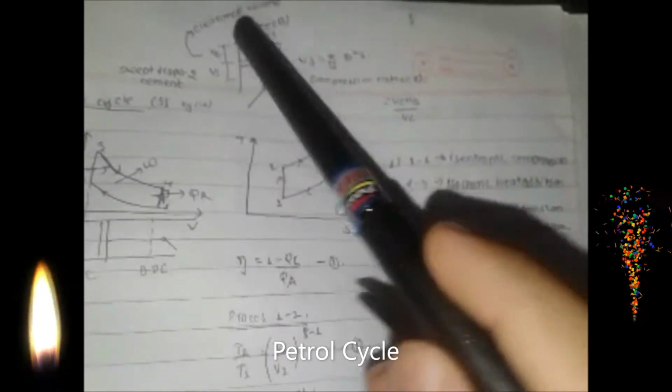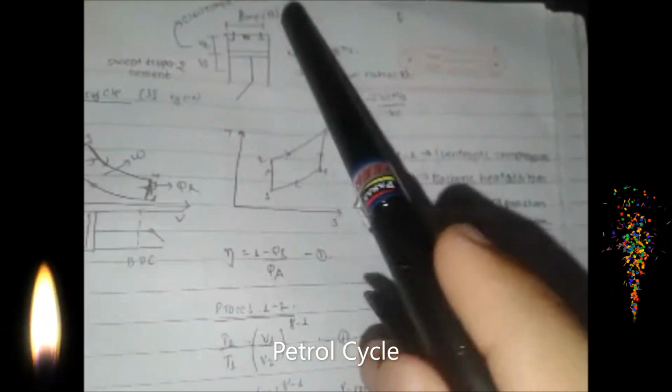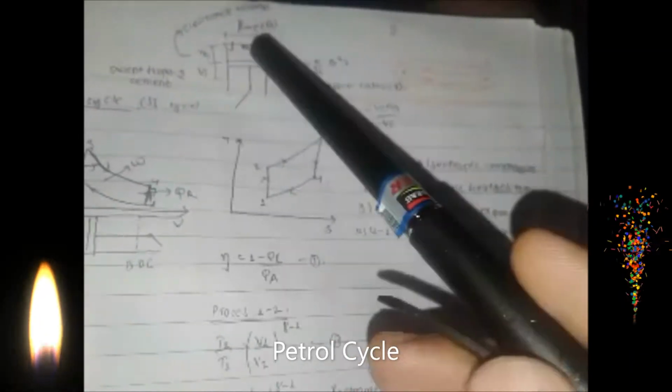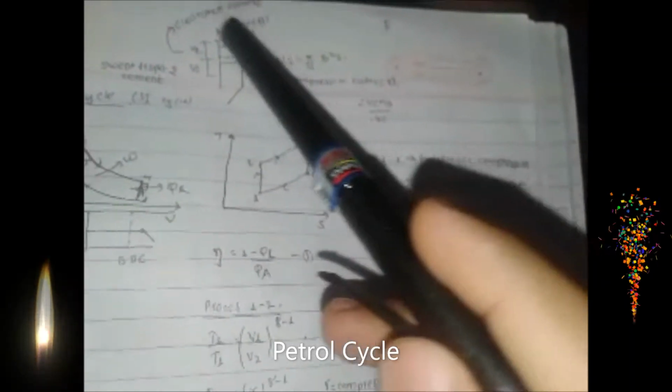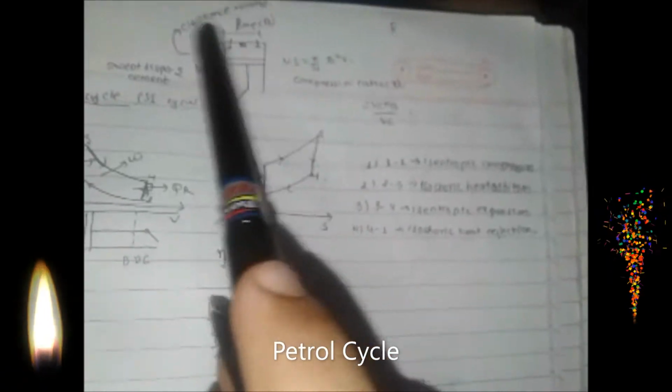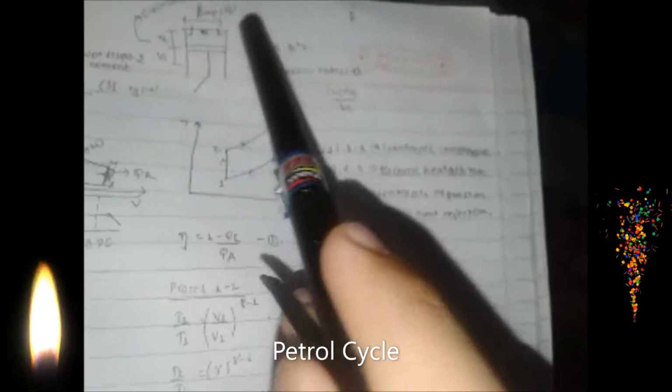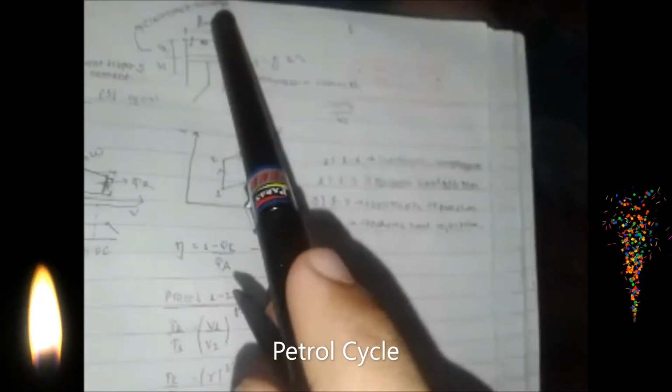And we know this is a piston, and this is a cylinder, and this is the bore. Why is the bore length given, or what is the bore? Bore is the diameter of the cylinder, that is double the radial distance, from one end to another end. The bore length is given to find the cross-section area of this piston.